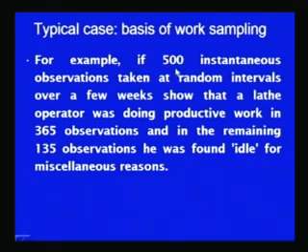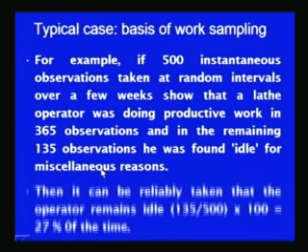Say, for example, 500 instantaneous observations are taken at random intervals over a few weeks, and these observations show that a lathe operator was doing productive work for 365 observations, and in the remaining 135 observations he was found to be idle due to miscellaneous reasons.